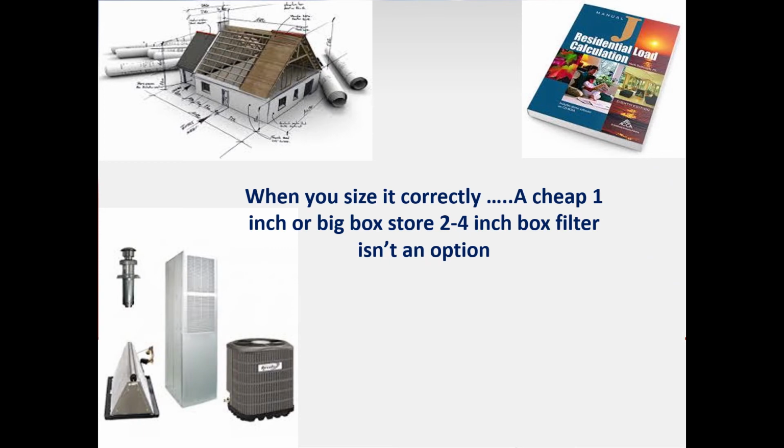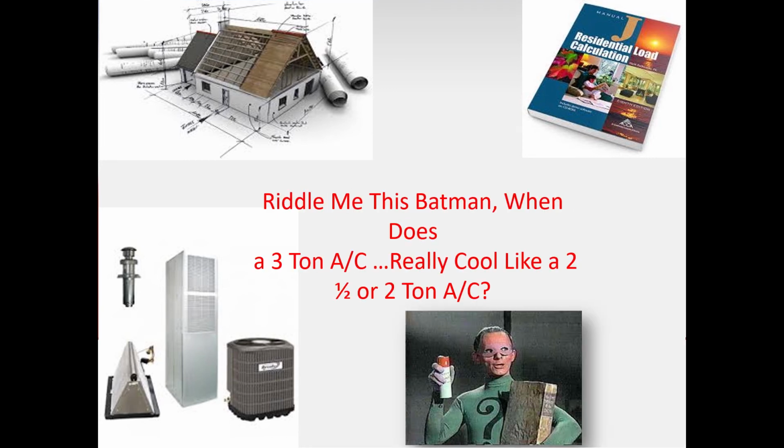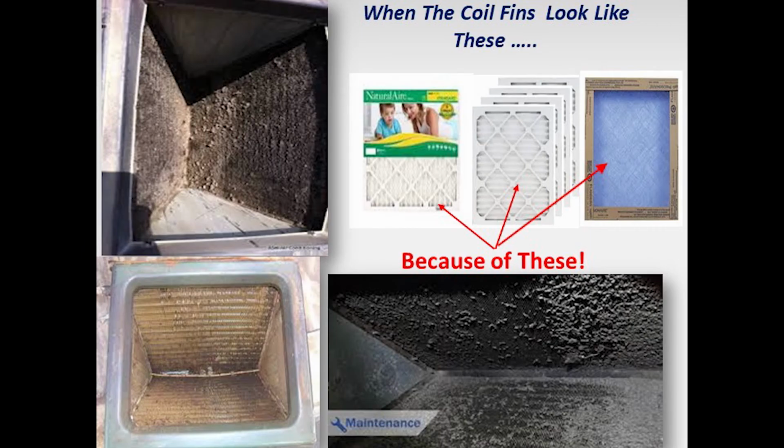And this just drives home the idea that your HVAC system, even if it's properly sized with Manual J, if it can't deliver the air it needs, you've reduced its ability to, for example, cool, both in terms of airflow as well as energy transfer. I think it's important to remember a dirty evaporative coil is going to cause an insulating effect, not just airflow reduction, but it's going to reduce the ability to cool the air down because it's insulating that heat transfer. And again, you've seen pictures like this. I think these are powerful when you're talking to a consumer.